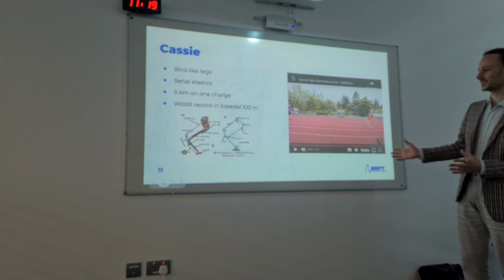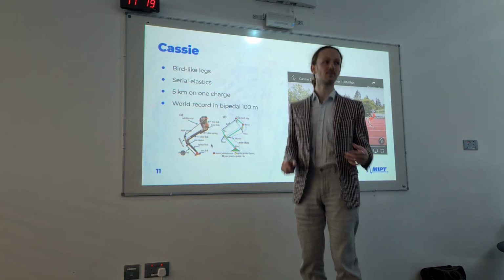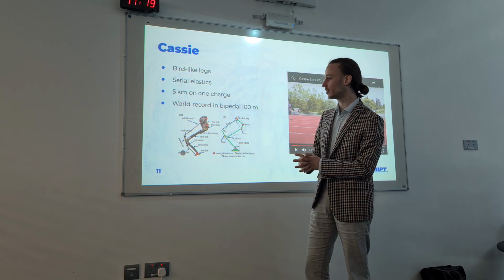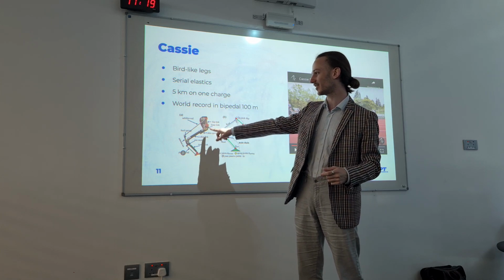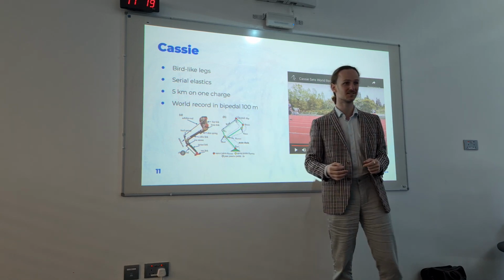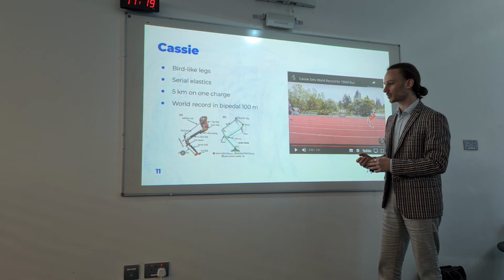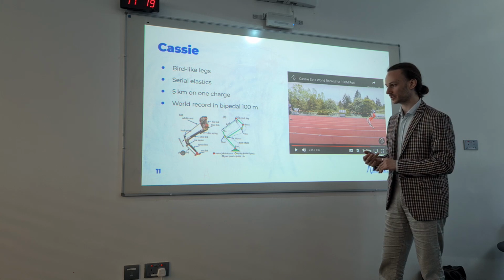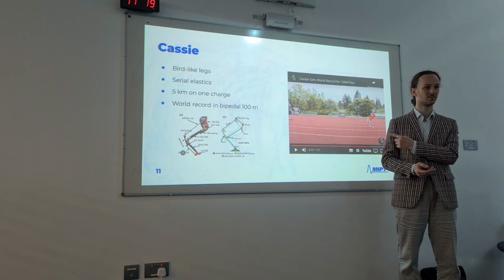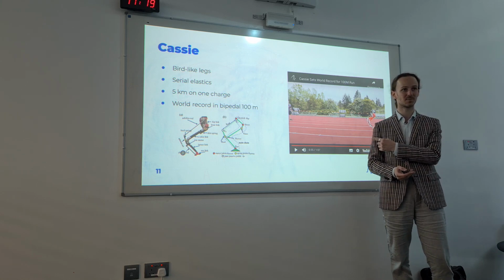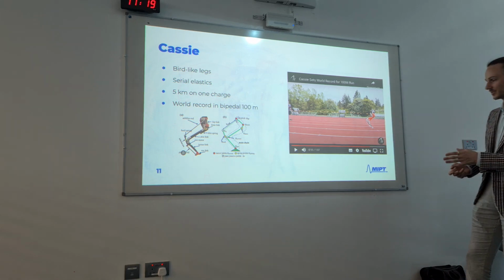The genius part of the design is not only the spring itself, which does the same thing as an Achilles tendon. The second cool thing is that the motors are moved upward. The legs are very lightweight, and this robot is robust to the ground conditions, to the surface condition. It was running blindfolded, by the way, no vision. It is capable of ascending the stairs blindfolded. So it's very robust in terms of the surface and conditions.